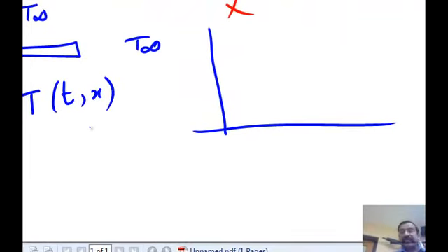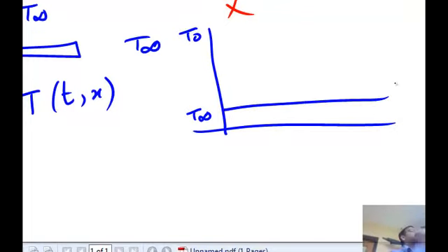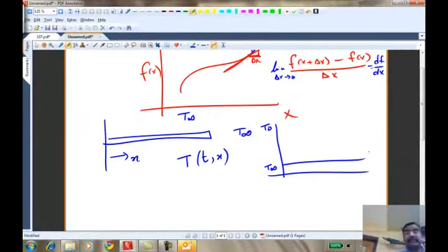And then I can say initially, if this is T infinity and this is T0, initially the temperature is at 25 degrees, and the base at time t equal to 0 is brought to 200 degrees. How will the temperature profile evolve, both with distance x and with time? Then you will get a profile at very small time. The profile may be like this. And as you wait longer, the profile will become like this. Okay, so each one will be for a different time, t1, t2, t3, etc.